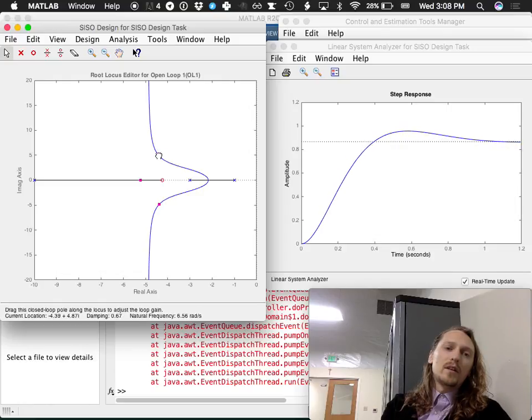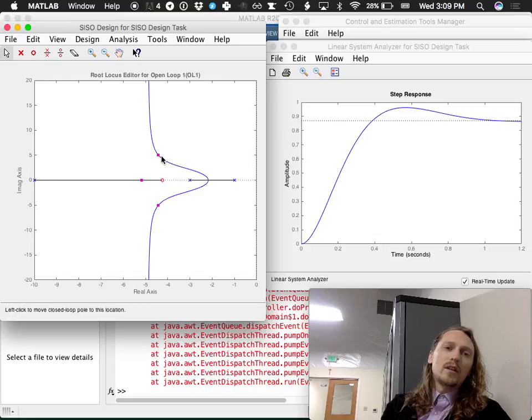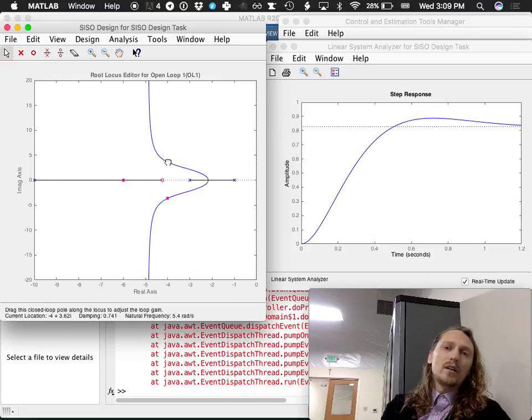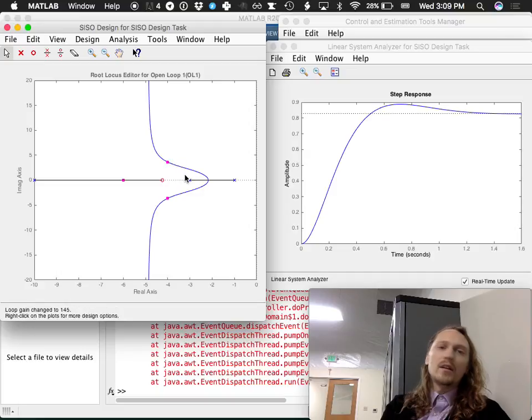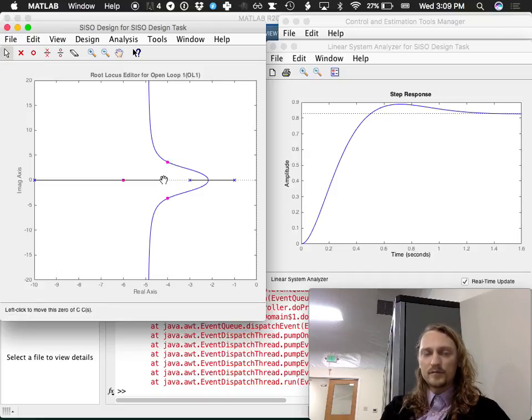So if you had chosen to move the zero further to the right, it would have changed the root locus more, but would that have been able to fix it, because that would change your angles. We solved this by solving first for the angles and then going that way. It would have been better to have done it the other way, to have changed the root locus so it was almost a straight up and down line on the value we wanted.